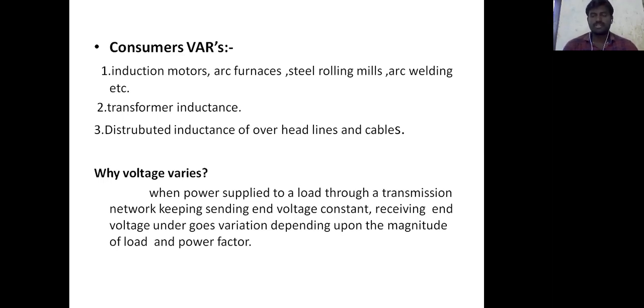The power factor reduces and the phase angle increases. With a lower power factor, the voltage variations are greater. As the phase angle increases, sin phi also increases, the reactive power also increases, and the change in voltage also increases.